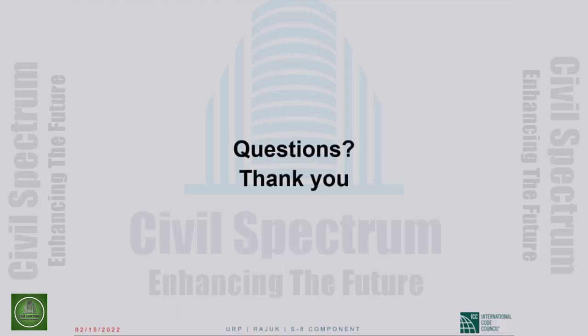So the next question is, in between modal analysis and time history analysis, which will give much better or accurate results? Which analysis do you suggest? I actually said this. Elastic time history analysis does not give you any more information than modal response spectrum analysis, as far as I'm concerned. You may get more numbers, but no new knowledge of significance.